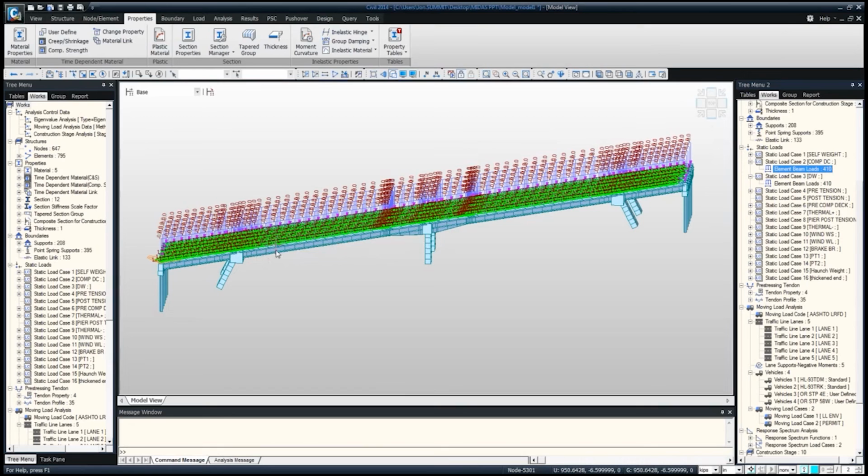And what I did was superimpose an assumed value of 3 inches, which should be a conservative value, and also assume that that increase in section depth didn't contribute to the effective composite section property. So that makes it conservative as well, because we assumed a slightly thicker haunch and then also didn't allow that to increase the section property.